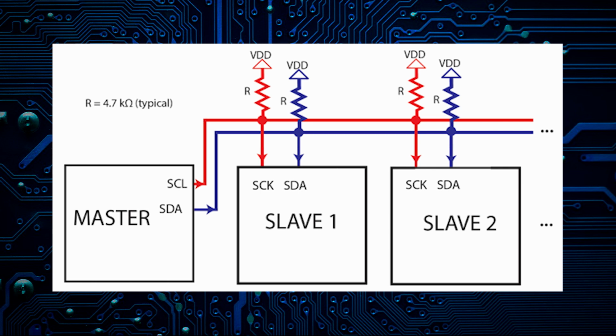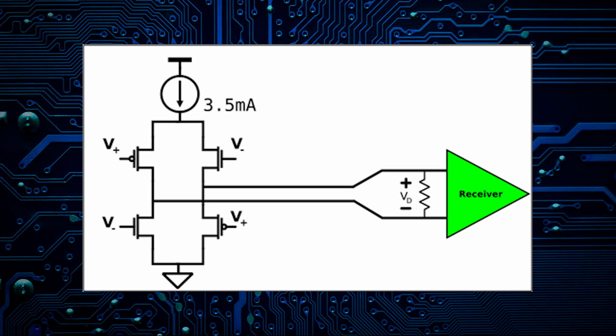While we have certain solutions, such as the RS232 interface for USART or a buffer driver for I2C, these have considerable limitations, especially with the communication speed. So, how can these protocols be transmitted over long distances? They use a different system called differential transmission.